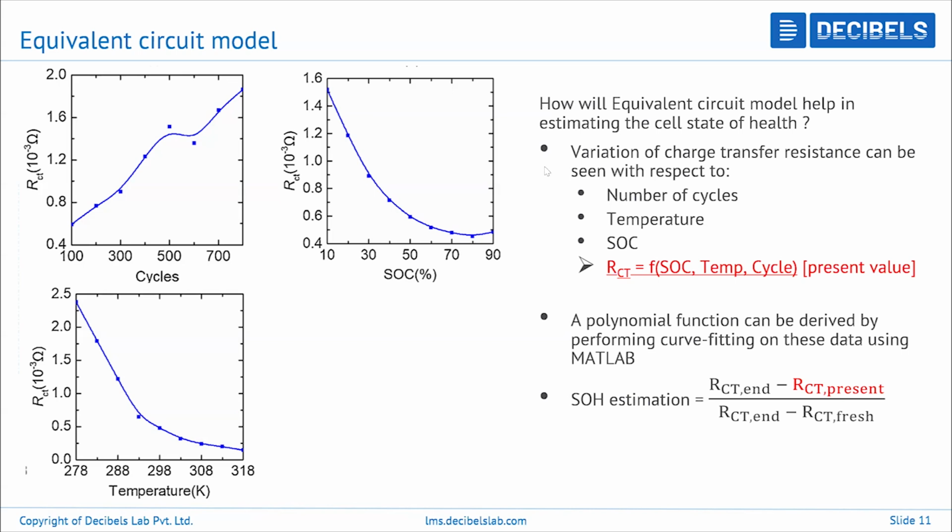One of the other fitting methods that you can use, you don't have to necessarily use MATLAB. You can even use ZView as well, which will return the values of the RC values, basically the inductance values, the resistive values, capacitive values, the Warburg values. And from there also you can implement that in an SOH estimation model and obtain the SOH of the cell. There are many software platforms that are able to derive the RC values by performing curve fitting and give the RC values as results. An example is ZView. There are some other ones as well, like Metrohm or BioLogic, which are able to do it.